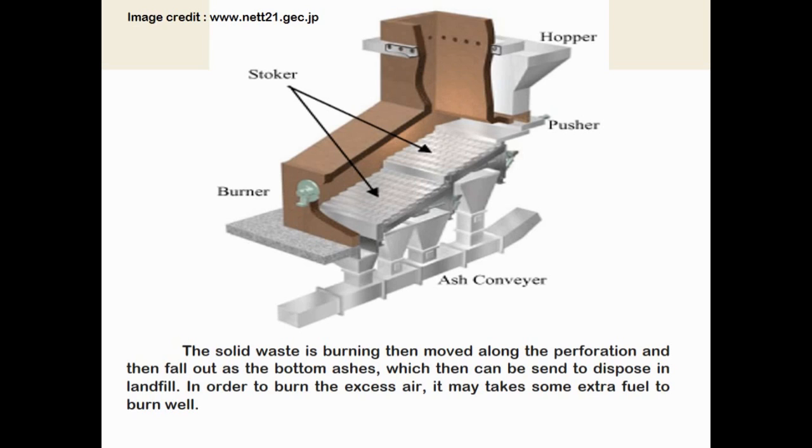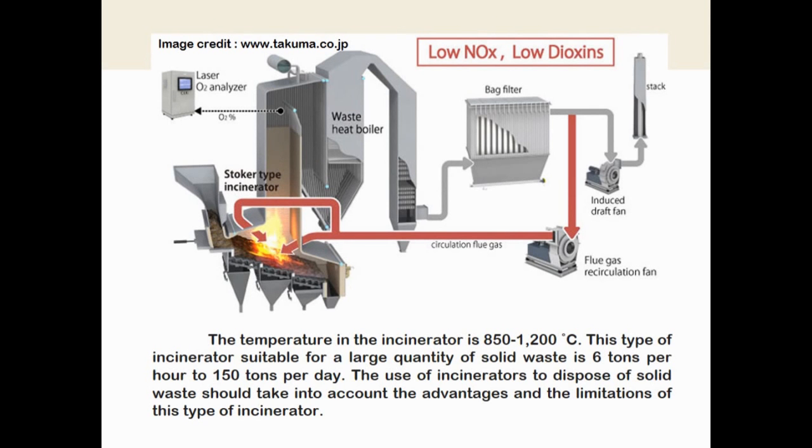The solid waste burns, then moves along the perforations and falls out as bottom ash, which can then be sent to landfill for disposal. In order to burn with excess air, it may take some extra fuel to burn well. The temperature in the incinerator is 850 to 1000 degrees Celsius.